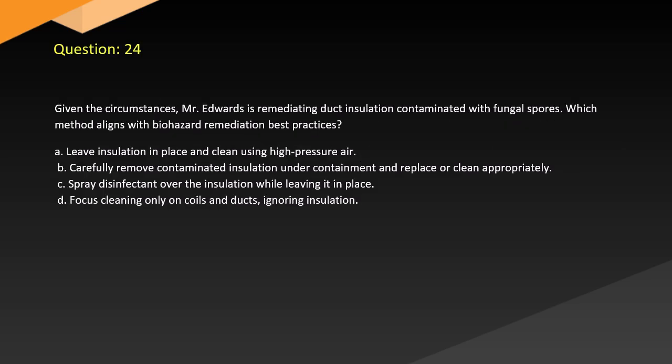Question 24. Given the circumstances, Mr. Edwards is remediating duct insulation contaminated with fungal spores. Which method aligns with biohazard remediation best practices? A. Leave insulation in place and clean using high-pressure air. B. Carefully remove contaminated insulation under containment and replace or clean appropriately. C. Spray disinfectant over the insulation while leaving it in place. D. Focus cleaning only on coils and ducts, ignoring insulation.